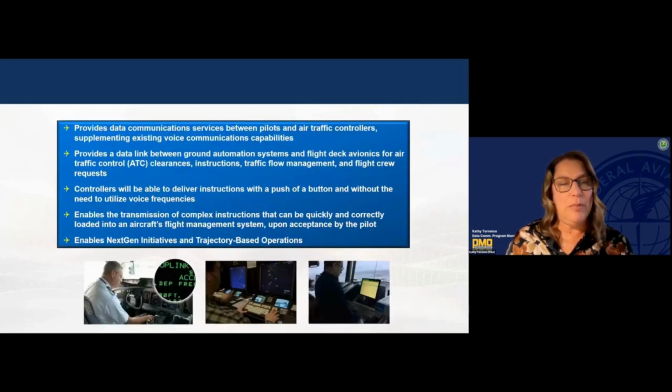So overall benefits here, again, we're providing those services between pilots and air traffic controllers, supplementing the voice communications capability. So there's no intent for Data Comm, or Datalink, to ever replace voice. This is a supplementary system. By introducing and providing that data link between ground automation systems as well as the flight deck. And the messages that we share include clearances, instructions, traffic flow management, and also requests from the crew.